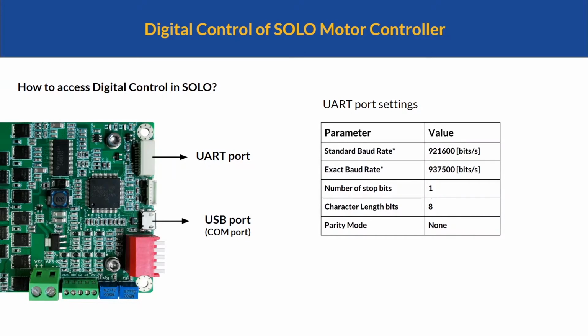If you use UART mode, the hardware settings for this particular communication are mentioned here. There is the exact baud rate, which is 937500 bits per second, and the other one is the standard baud rate, which is the baud rate that you might find on PCs or on modules that don't support the exact baud rate of Solo. In both of these baud rates you can work and send and receive commands from Solo.